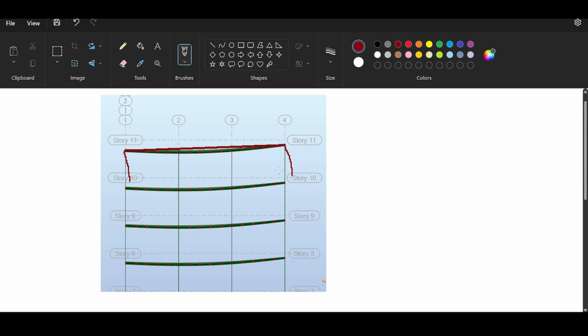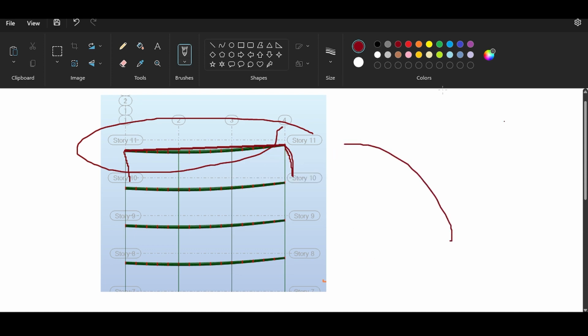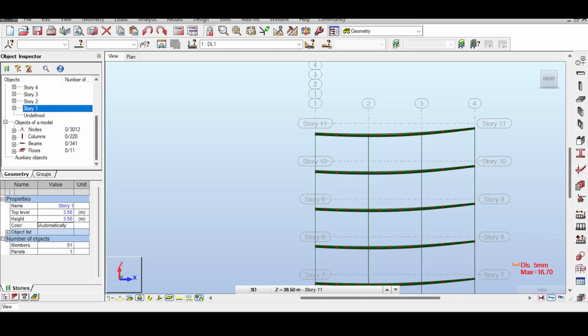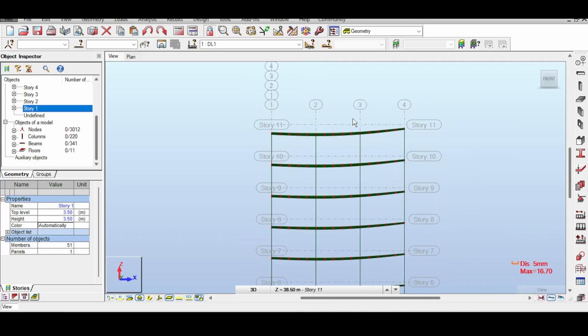If I had a rigid joint, this entire slab would cause the beam to rotate, causing the entire structure to incline. So this, ladies and gentlemen, is the real reason why you have twisting and turning in a structure, even if you load it perfectly vertical.